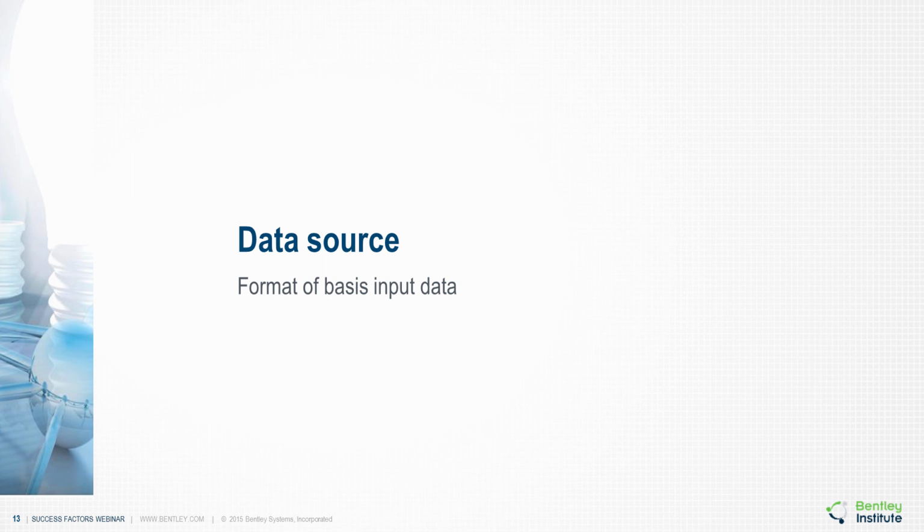The format of the available input data that defines the geometry to be modelled and the type of MAXSURF model which is required will have considerable impact on the optimum workflow. In this section we should look at some of the common sources of input data and then review the level of difficulty to obtain a tri-mesh or NURBS based model in MAXSURF.